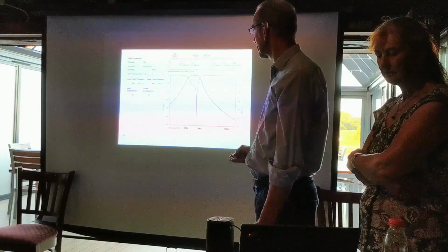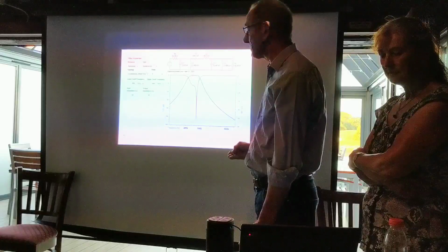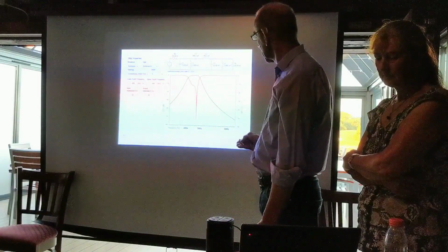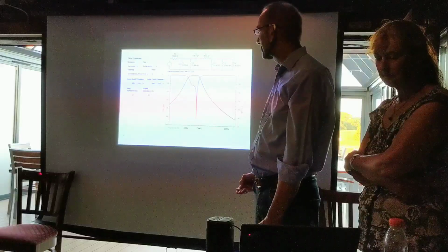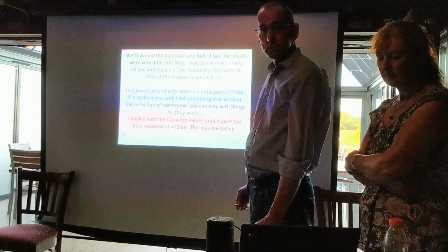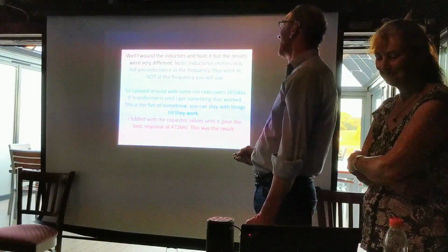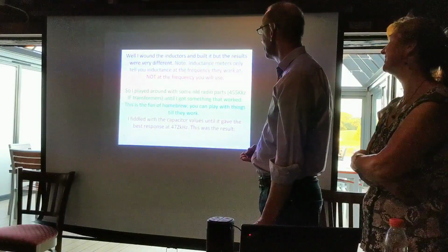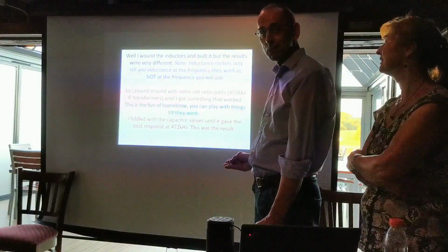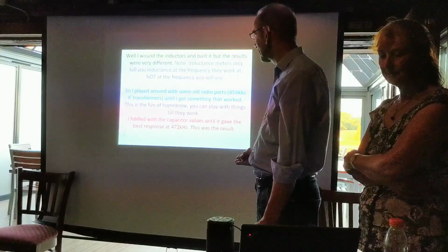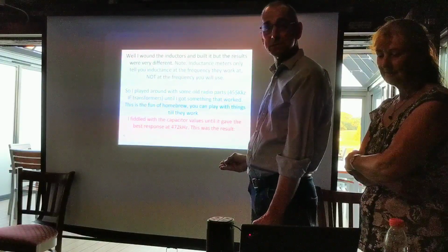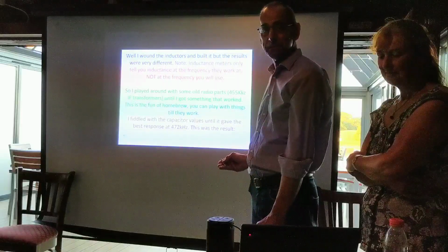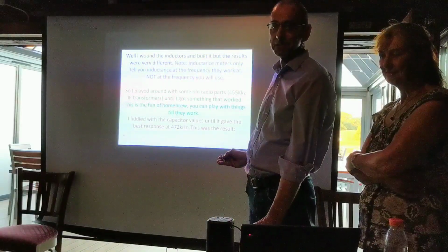And here's what this website gave me. All the values, absolutely marvellous. And look at that, absolutely fabulous. So I built it and it didn't work. I carefully wound all the inductors and used my eBay inductance meter. Of course, what you have to remember is that inductance meters measure at the frequency they work at, not the one you're using. So the fact that the inductance meter tells you something doesn't mean that's what's actually going to happen.